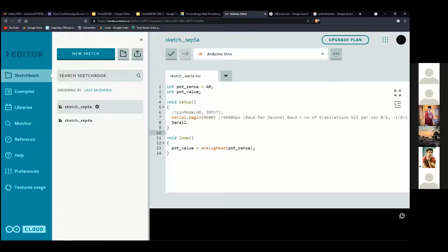There will be 3 different levels. For those things, your bits per second won't be applicable. What will you use instead? The baud will be 3, because in our data transmission you have 3 different transitions: -1, 0, or 1. So your baud will be different.